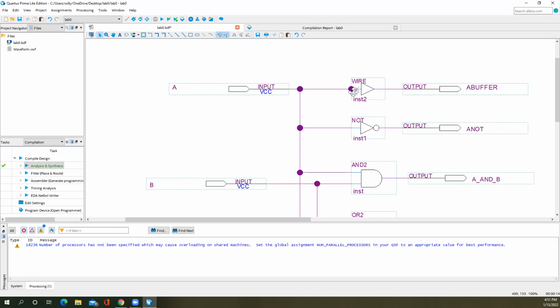Sometimes, see how there's a junction box here, but the important thing is this X in here. Sometimes when you actually draw too far into here, Quartus will act like you shorted out the circuit. So when you do that, you want to get rid of that. So let's say we did that before. To get rid of it, I can just click on a highlight, hit the delete key, it goes away. And once I make a change to the circuit, I need to save it. So I can say file save, or Control S does the same for me.